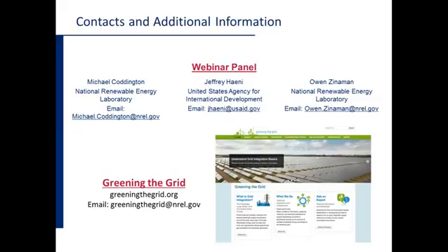We've demonstrated in the lab and in practical experience that inverters don't tend to create unintentional islands when the utility goes down. We've tested this in the lab, and the probability of an island forming is incredibly low. But even in the case of an island forming, the generation of the photovoltaic would have to match the load pretty exactly, and that's extremely unlikely because people turn loads on and off all the time.